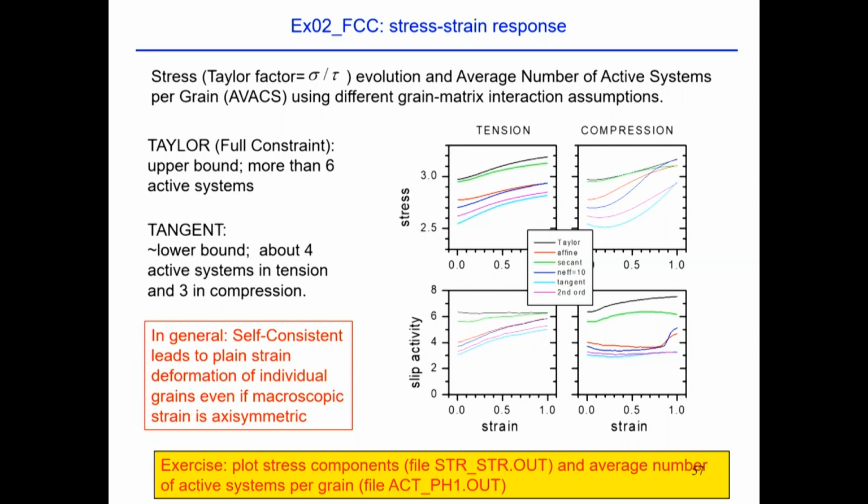So what is plotted here is the stress strain evolution for tension and compression, and the activity of slip systems. I will explain. First, the stress strain evolution.